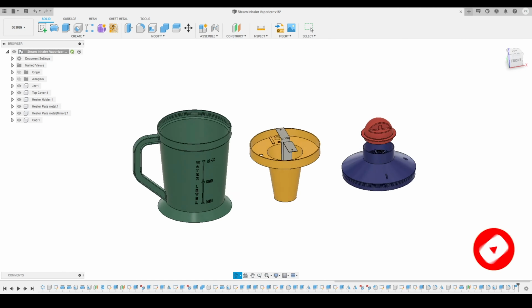So I will go to the create panel and activate our line tool. Here you can see this is my line tool, and I will start creating the shape of my handle. I will create a horizontal line like this, then come to the bottom at a particular angle, and connect from here to here. So this is the shape we got, and now I will start defining the dimensions to make the handle look more correct and in the right scale.